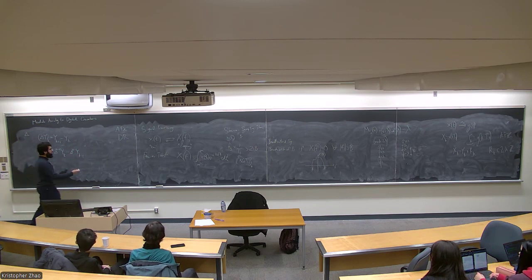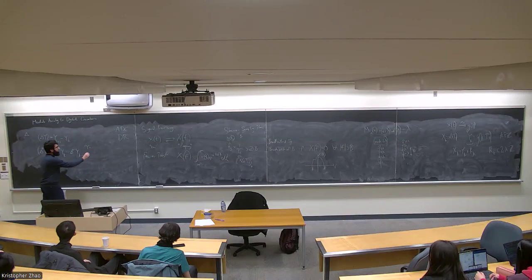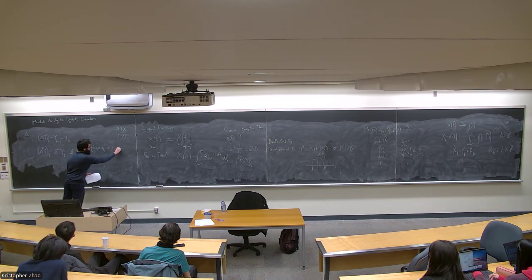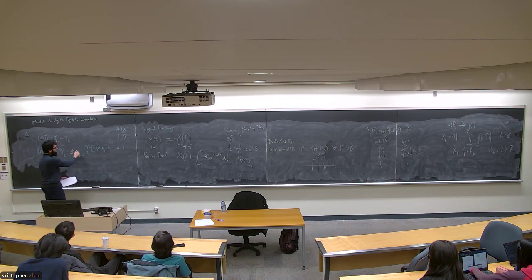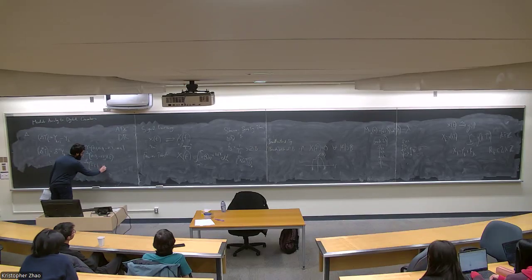We can also consider a simple example of this operation. Let's say we have 4 samples y, given by 0.1, 0.4, minus 0.7, minus 0.5. Applying this delta operation will just compute consecutive differences. So we have 0.4 minus 0.1, which is 0.3, then minus 1.1, then 0.2. And if you apply this operation one more time, that will give minus 1.4 and 1.3